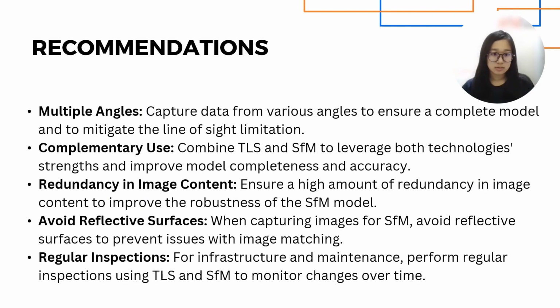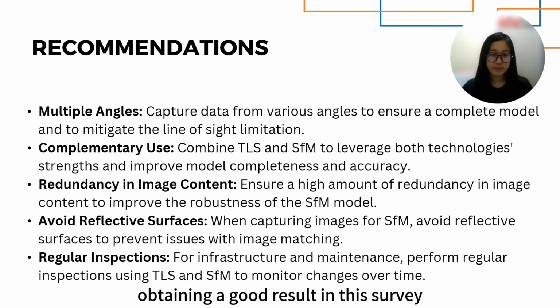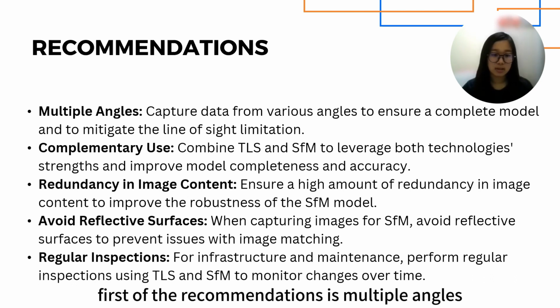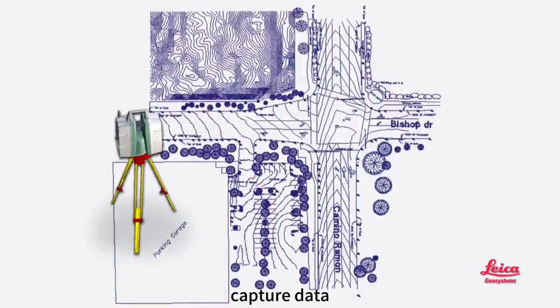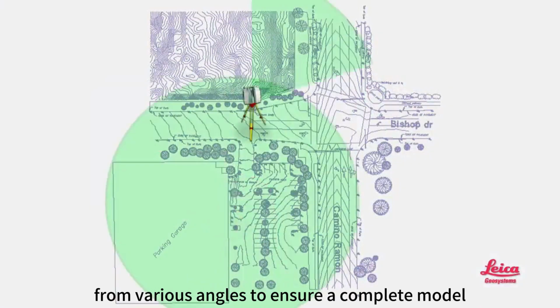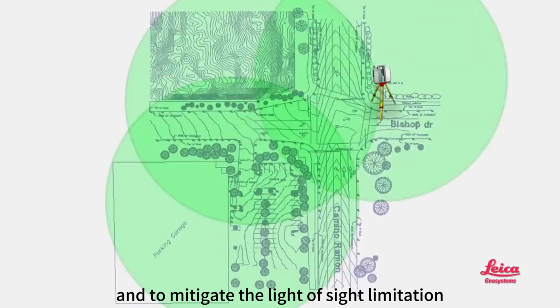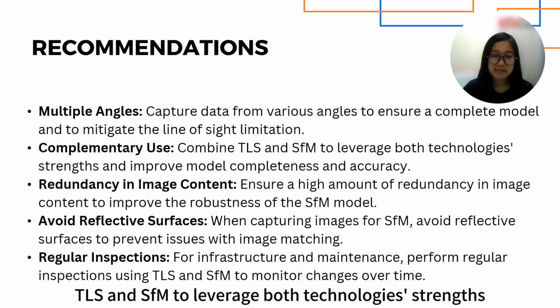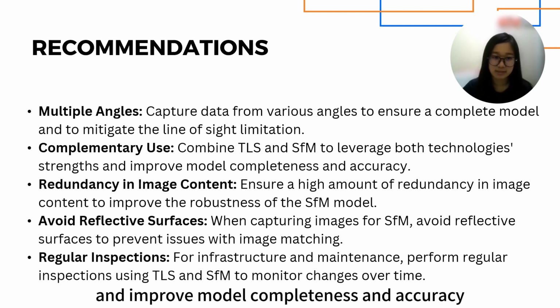Next, these are the recommendations for obtaining a good result in this survey. First of the recommendations is multiple angles. Capture data from various angles to ensure a complete model and to mitigate the line of sight limitation. Second is complementary use. Combine TLS and SFM to leverage both technologies' strengths and improve model completeness and accuracy.